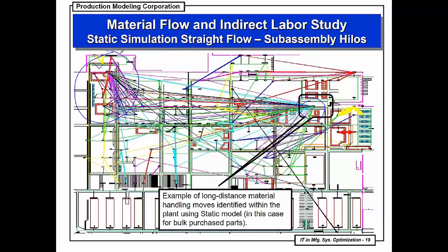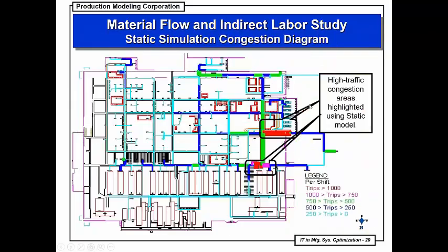So this was on your left-hand side and one on your right-hand side. Again, next is basically using the aisle to make the material flow through the aisle. This way you can see where your most congested aisles are. As you can see, those highlighted in red showed the aisles where you had high material flow activity. That means it might be your tuggers, your AGV system, your forks flowing through those aisles. So again, it gives a very good representation of the congestion happening in your facility.